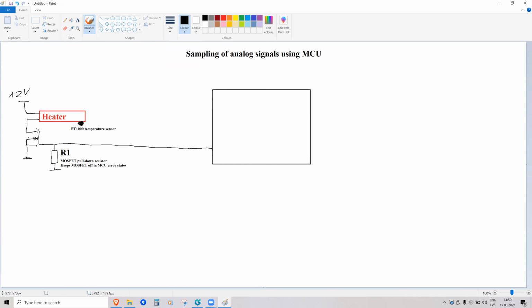It's right there. You can glue it, or you can use a screw and screw it somehow. Screws are usually better because glue can wear off in time, but if you screw it to the metal with some screws, usually they last much longer. And if you use metal clips, they are even better because they always apply some pressure. So metal clips are even better in this case.